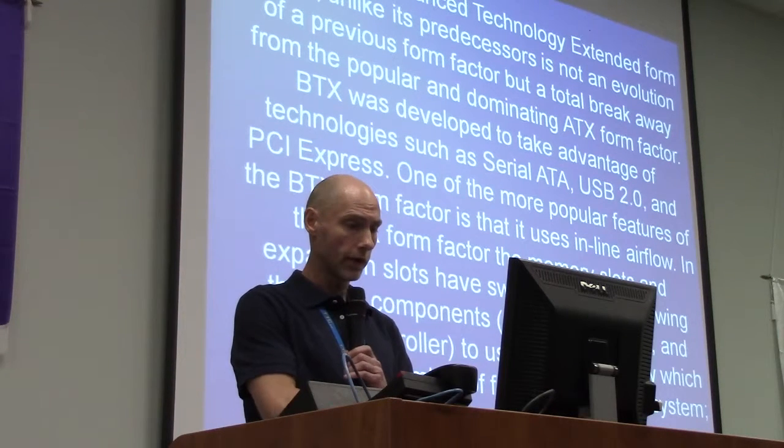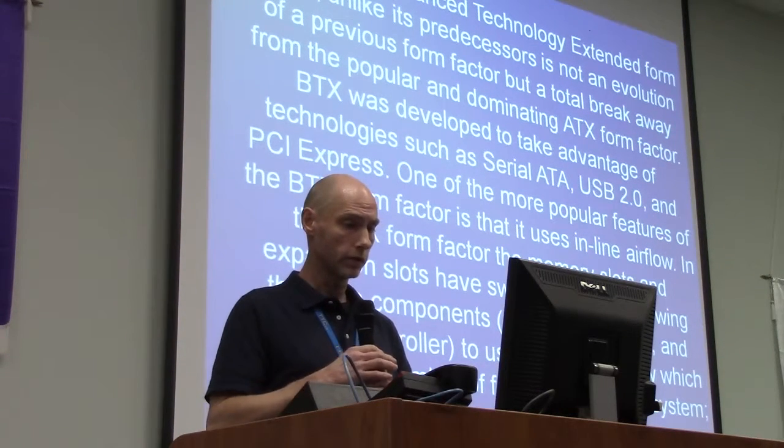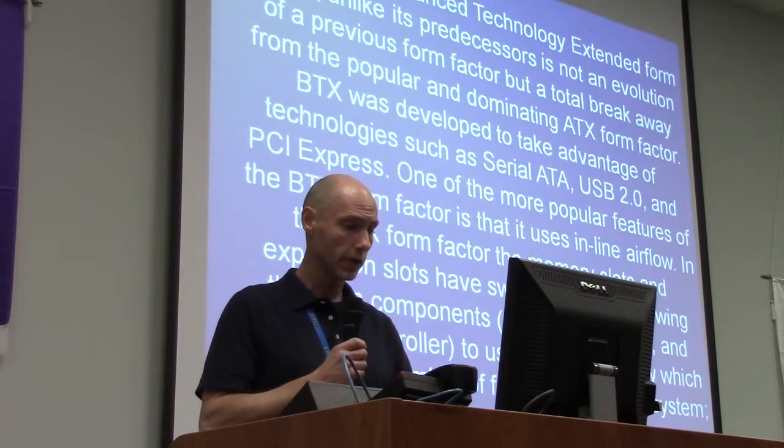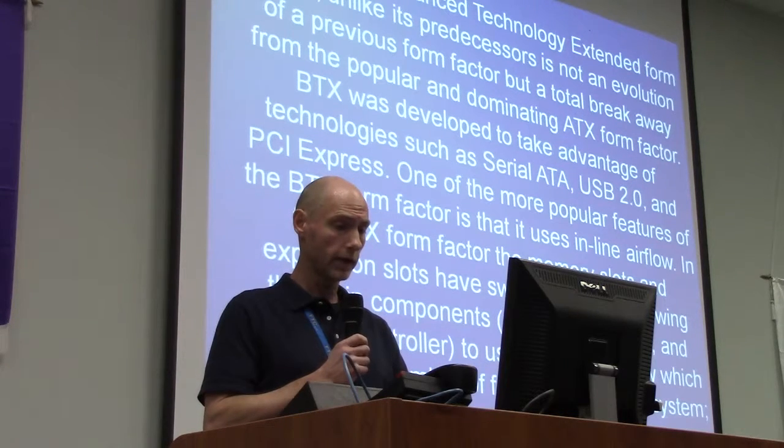One of the more popular features of the BTX form factor is that it uses inline airflow. In the BTX form factor, the memory slots and expansion slots have switched places, allowing the main components, the processor, chipset, and graphics controller, to use the same airflow, which reduces the number of fans needed in the system, thereby reducing noise.